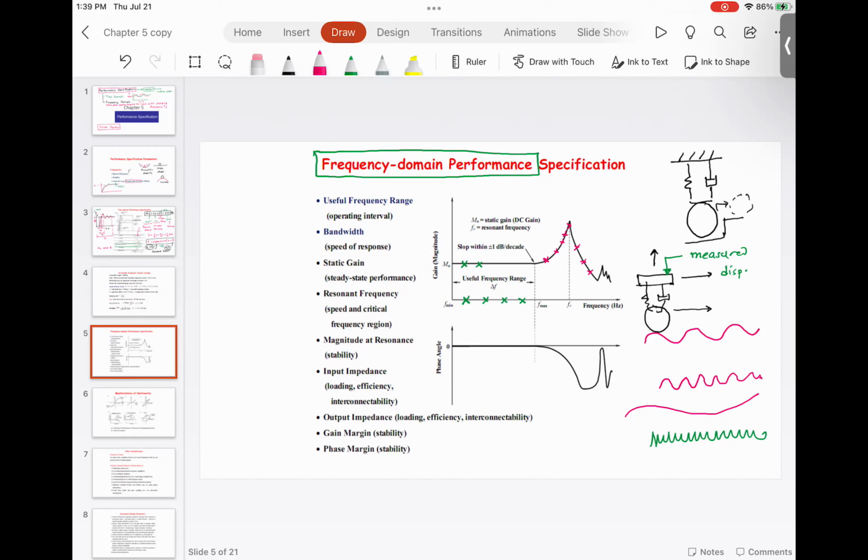And then gradually, as the speed is decreased, the washer settles down. So the response of the washer, a dynamical system described by spring, mass, and damper, is dependent on excitation frequency.